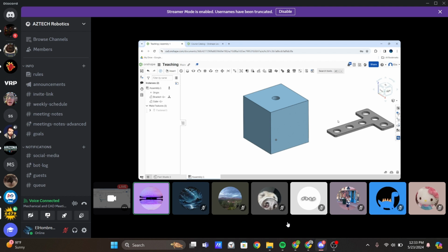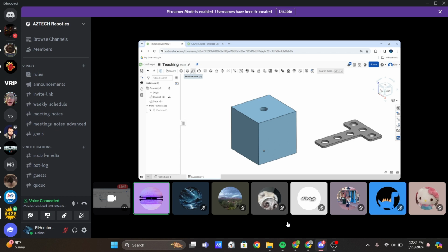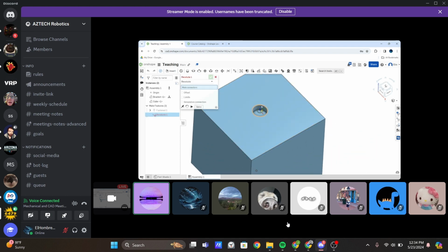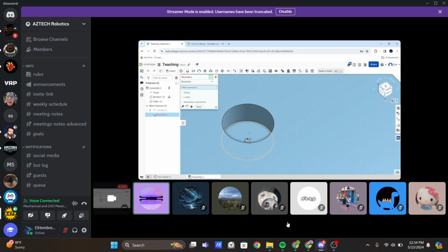So the one that I would highly recommend using otherwise would be the Revolute mate. So the Revolute mate, if you hover over all of these, it tells you about exactly which degrees of freedom it restricts the piece down to. Revolute basically will allow something to spin or revolve around something else, another point. So I usually use these as an imaginary rivet, per se. If I click on this one, I want to attach this bracket now to this cube. So I will start by putting a Revolute mate. Also be careful, because you can see when you hover over things, I can either put a Revolute mate on this face down here, or on this upper face, and those will be 2 different things.